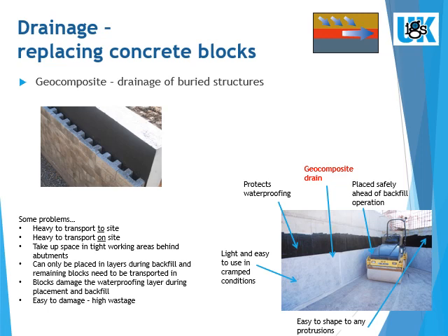Any buried structure is likely to be subject to groundwater pressures from one side. Retaining walls, culverts, basements, underground water reservoirs. Typically, the water table is lowered to the base of the structure and drained or pumped away, leaving it dry.